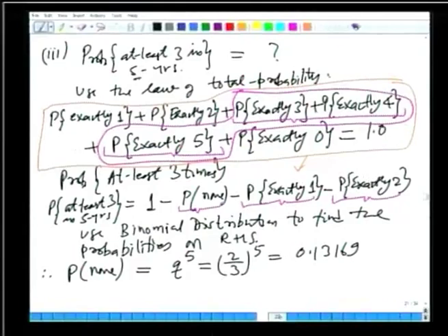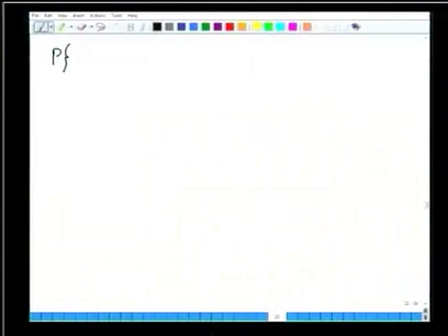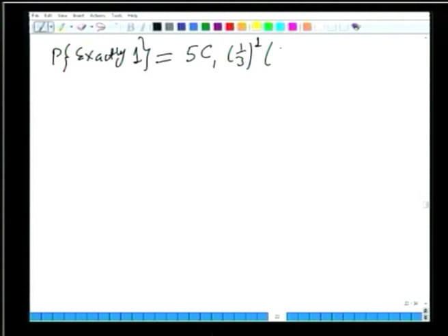Let us move on. What we have to find next is probability of March runoff being greater than or equal to 4 centimeter. This event occurs exactly once in 5 trials. Will be equal to what? It will be 5C1, then P to the power R. What is R? R is 1, and Q to the power n minus R. N is 5, R is 1, so it will be 4.